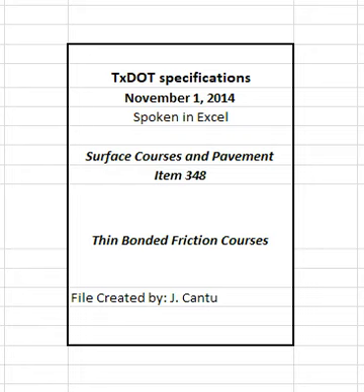4.4.2.2.7 Approval of JMF2. The engineer will approve JMF2 within 1 working day if the mixture meets the requirements in Table 5, as well as the master grading limits and binder content shown in Tables 7 and 8. 4.4.2.2.8 Approval of Lot 1 production. The engineer will authorize the contractor to proceed with Lot 1 production, using JMF2.